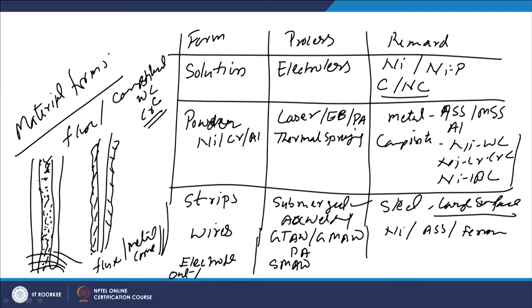So, in case of the metal cored electrode, besides the flux, we also include the constituents in powder form of the elements that we want to introduce, which may be in the form of chromium or nickel or any other element that we want to add in the bead-on-plate weld, or we can add suitable constituents in the form of carbides, borides, etc., so that they can be incorporated in the bead-on-plate weld.